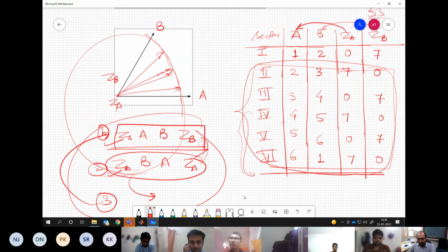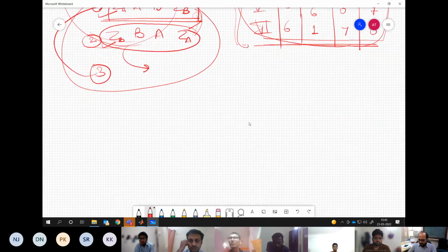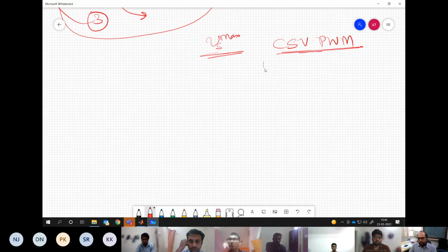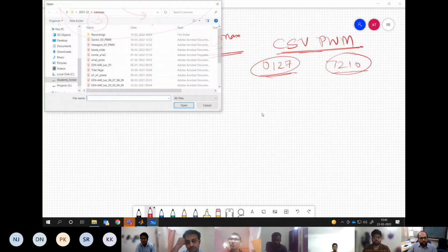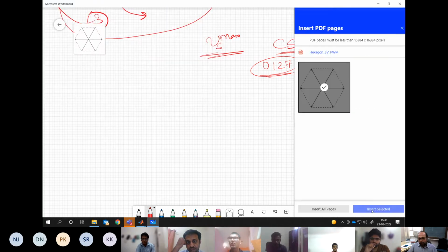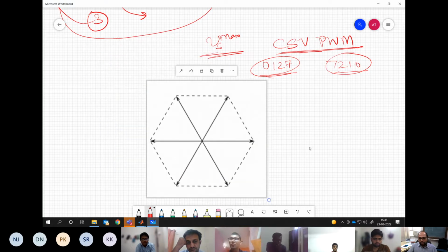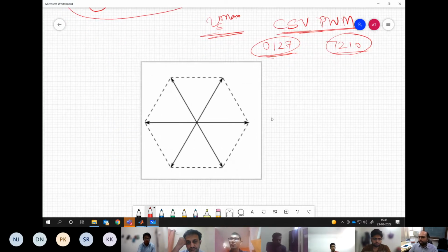Okay, so one last point I will give for the space vector PWM is what is the maximum voltage which you can realize using the conventional space vector PWM. And we are talking about the conventional space vector, which means no bus clamping and all these things. So simple sequence 0, 1 to 7 or 7 to 1, 0, either of these is involved for realization of samples in the sector. Now, the question is what should be the limit of maximum voltage which we can realize using the conventional space vector PWM?